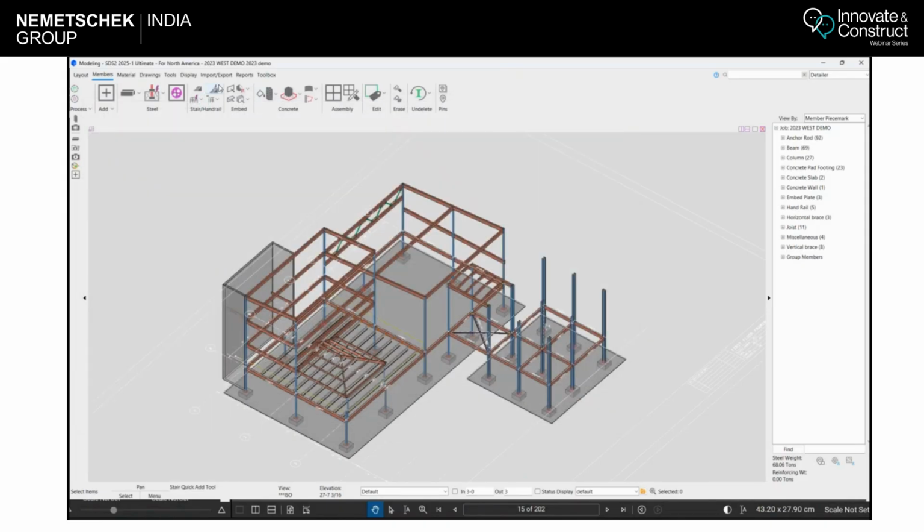Then this is for quick commands. So I can add a stair, quick stair, which I have already shown in my video. Okay. Then I can add a handrail to a stringer. I can add a flat handrail. Okay. This is for modification. So if I added a handrail, I can adjust my railings, spacing, or move the whole handrail, and all those kinds of things I can modify.